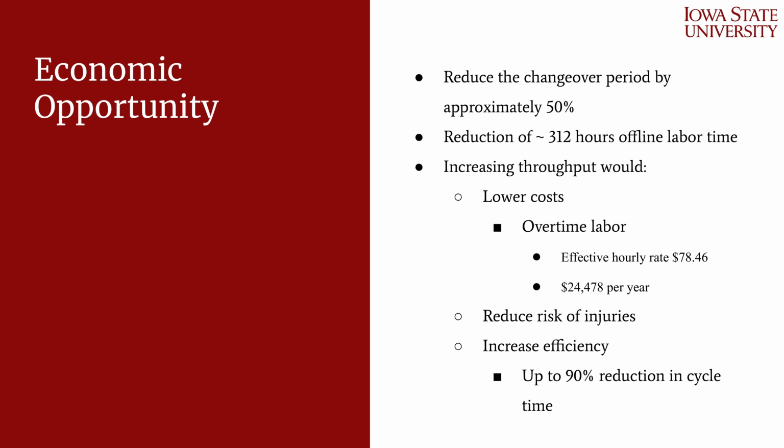Additionally, we found that CNC is a significantly safer process, and the risk of injury to the operator is significantly lower when we decrease the amount of product being run through the hand trimming process. Additionally, there are significantly better cycle times for parts run through the CNC process. We discovered up to a 90% reduction in cycle time for parts with Winnebago and also parts in industry references.